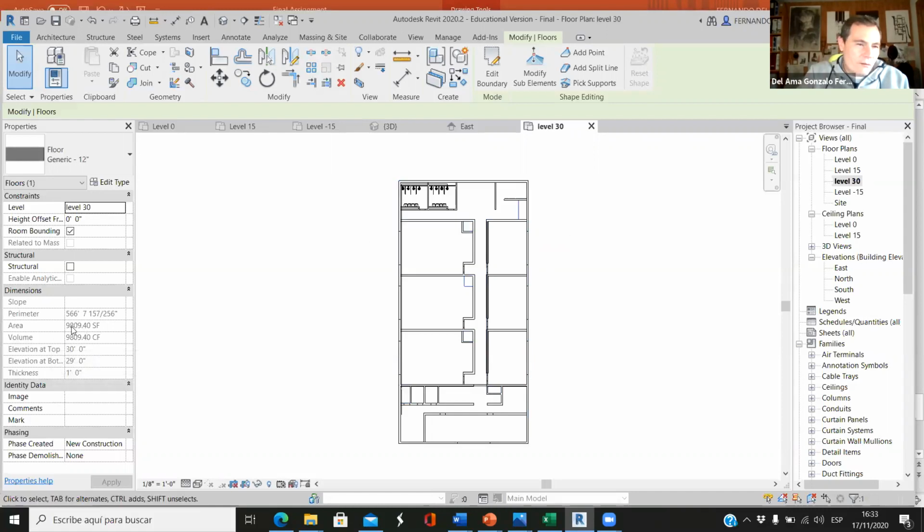It's almost 10,000 square feet. So now we have to make decisions, based on the shafts. If you see that we have shafts here, all these rectangles, those are shafts. Through these shafts, we have to place the storm water that comes from the flat roof. So if we divide this in 4 sections, 10,000 divided by 4.